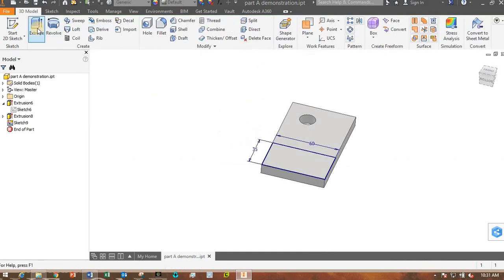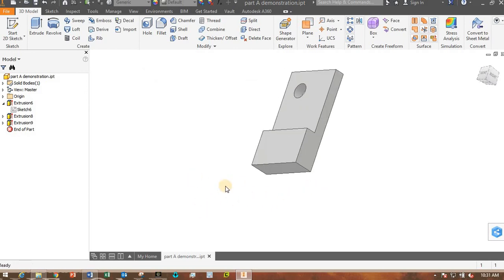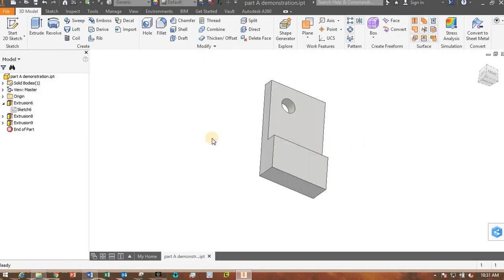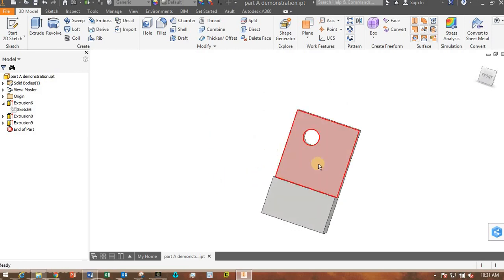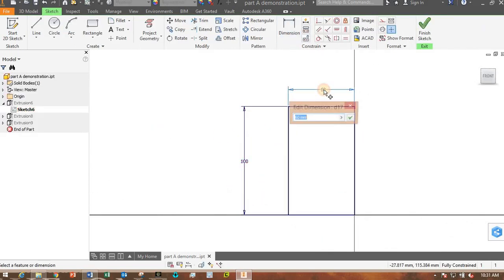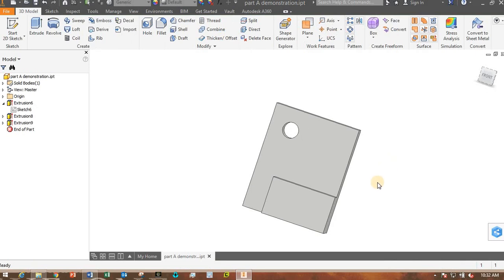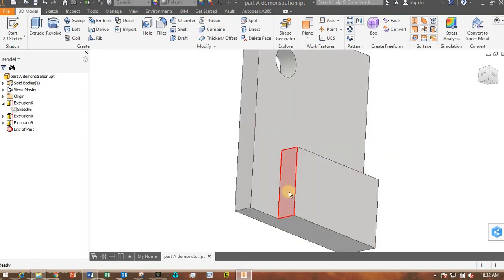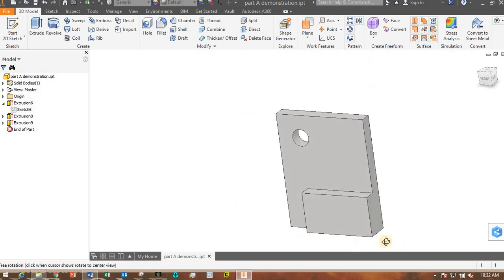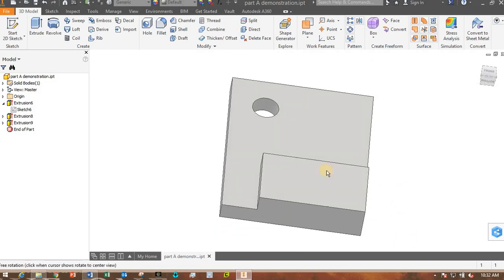Let's say you finish that sketch, you make an extrusion, and here you have this part, it looks good, and then your boss comes along and says, oh, wait a second, I want the width to be different. So you say, okay, sir, no problem, double click here, and you make it, let's say, 80 now. Oh, what's the problem here? Guys, look, this did not change. Why not? Because I defined the length of this line here to be 60. But the intention of the design is that this line and this line always be the same length.